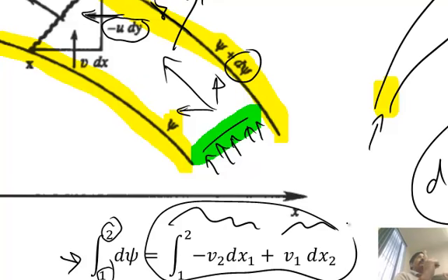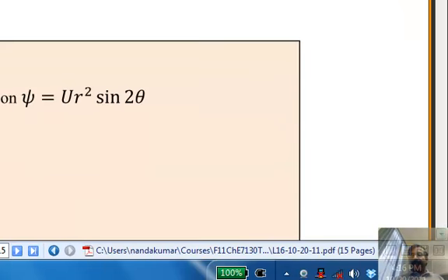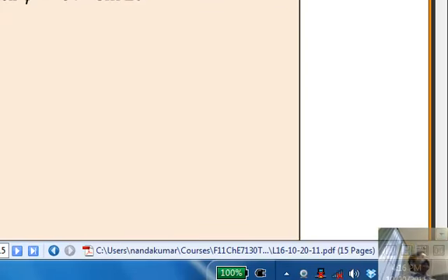So it's two-dimensional flow, right? So dy times 1 is an area. Similarly, dx times 1 is an area. Okay, so that's why we interpret this as the flow rate. So that shows the difference between two streamlines is directly a measure of the flow rate, and that's another nice feature of it. Here is your think, pair, share exercise.